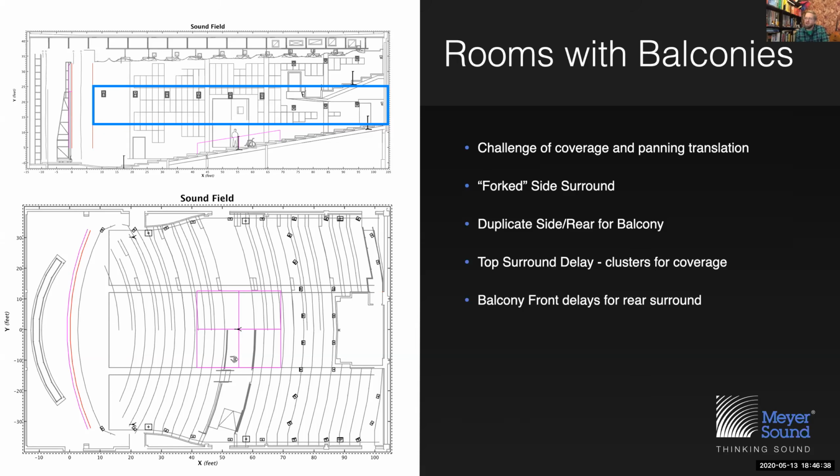And okay, if we try to shoot all the way to the front row, we're going to smoke those back rows. They're not going to have a good time if something hot comes out of those speakers. So what we would have normally picked product-wise, we downsized to only cover under the balcony. And if you look at the section view of the balcony face, we chose the larger loudspeaker to be mounted on the balcony face to basically pick up that signal and shoot it farther from a better position to get to those front rows.